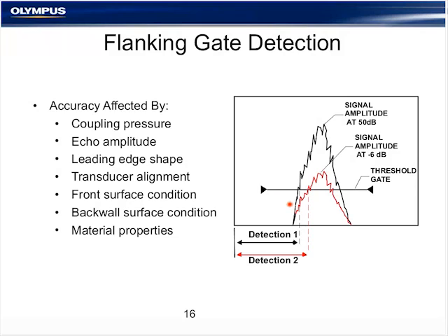What's very common in a corrosion inspection with a flaw detector is to make a thickness measurement based on the first crossing point of this echo over the gate. This is a flank detection or an edge detection. Unfortunately, as you're moving across the inspection piece, and certainly when you're dealing with surface roughness, the attenuation of the coupling layer, the presence of the coupling layer, there are a lot of factors that can figure into having this signal strength decrease as you move over the part.